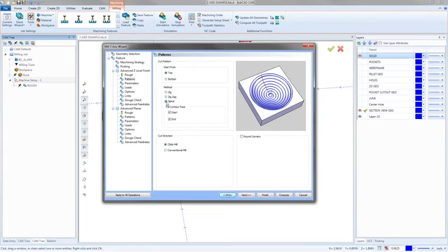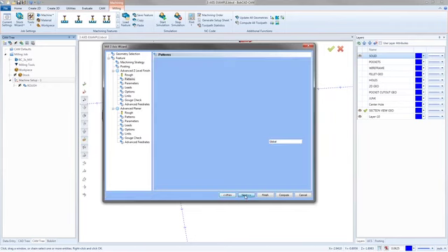I don't really like the spiral on this one unless I'm doing more of a helix hole. If I'm trying to get a hole made, I can use a spiral on that. But whenever you're doing anything with a Z level, you want the steepest wall you can get. 90 degrees, really down to about 30, 40 degrees, 30, 40 degrees being where it starts to do a bad job. So I'm going to go with a zig, just keep everything moving in the same direction.